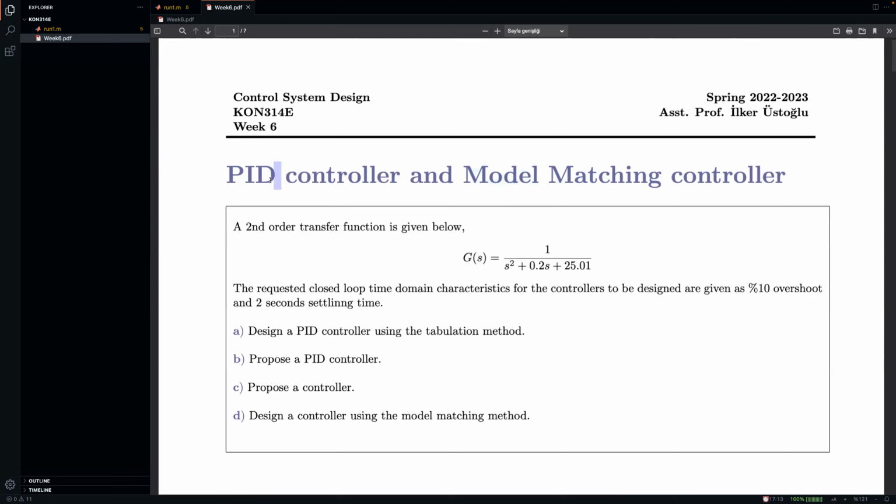But other than that, PID controller design depends basically upon the practical application itself, but you also have to see what the method is trying to do. Sometimes you have to use pole zero cancellations, sometimes you want to avoid them. So you have to get this feeling of the PID controller for what to do. And in practical applications, you're not going to use the PID controller on its own like it is. You have to go for some connections and special limitations.